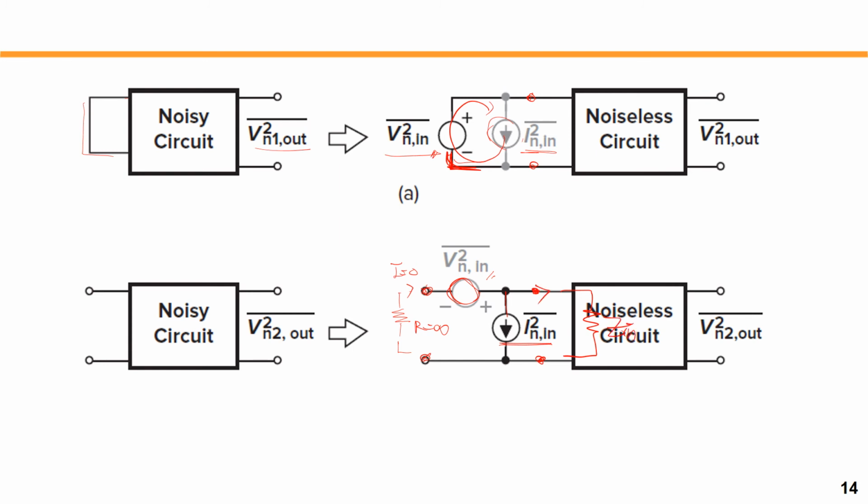That will create a voltage drop, right? That affects the output. So for both cases, you will measure the output voltage. Those voltages must be matched, must be the same, right? It will show some different value, but it must match in both cases. Therefore, this kind of voltage and current noise, the input referred noise voltage and current, properly represents the actual noisy circuit, right?